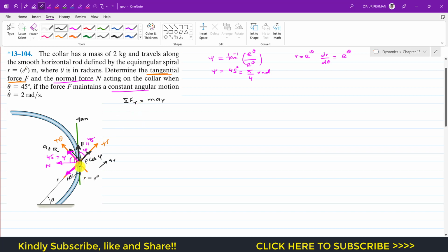So we have the sine component of N in the negative r direction, so I will write minus N sine of psi, and psi is 45, remember, and this is the cos component of F which is acting in the positive r, so I will write plus F cos of psi, and this will be equal to the mass. Mass is 2 kg, so 2 times a_r. Now we need to find a_r. We have this equation from the kinematics, so we can find this a_r.